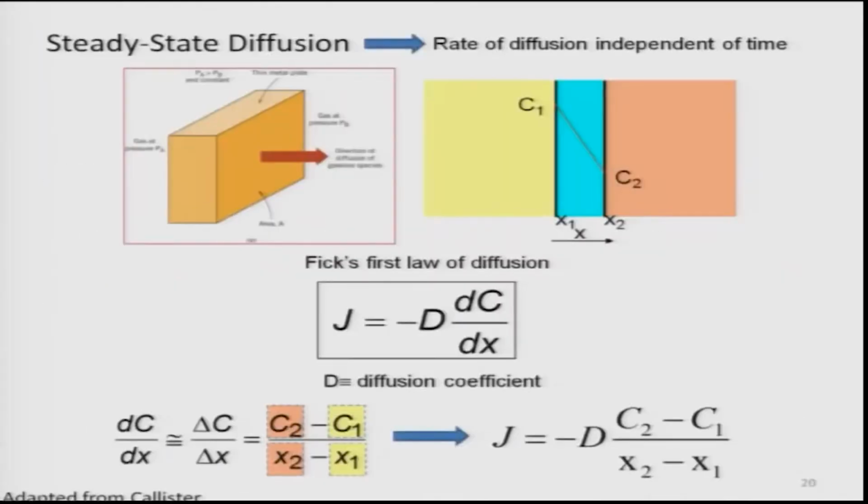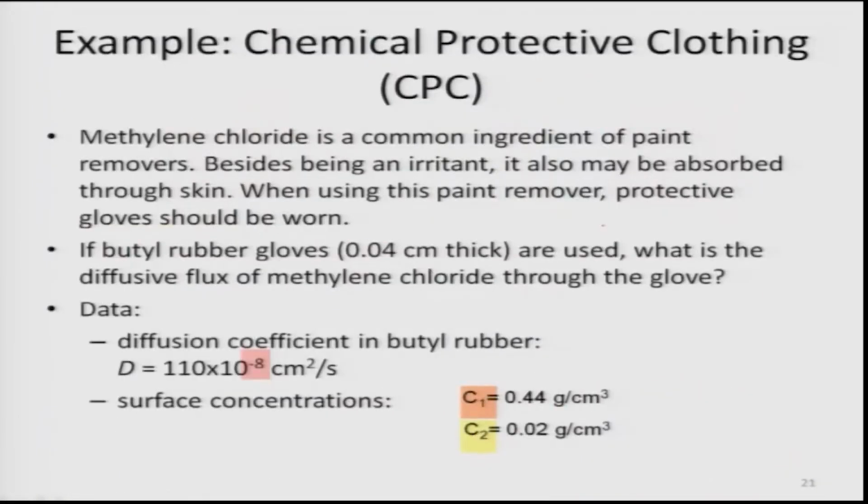Okay. So, I already explained this, just to tell you that this is Fick's law. We can always do simple maths, and del C by del x can be written as (C2 minus C1) divided by (x2 minus x1), therefore, on a macroscopic scale we can write Fick's first law as J equal to minus D times the difference in concentration divided by the difference in distance. Okay, so let us not spend more time on that. We will get back to it in the next lecture, Fick's second law, how to solve these different aspects and how we can explain different phenomena which you observe in real experiments.